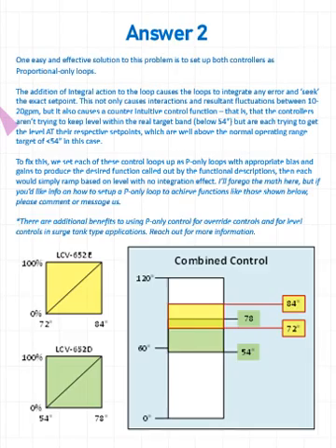So one good solution that accomplishes the functional description very clearly is to use proportional only control loops, because basically what that control function described was for the small valve to start opening at 54 inches and to be full open at 78. So that, if you look here, that's a proportional response. And that's fairly easy to do. You can have two loops in this case. You could have three, four, whatever.